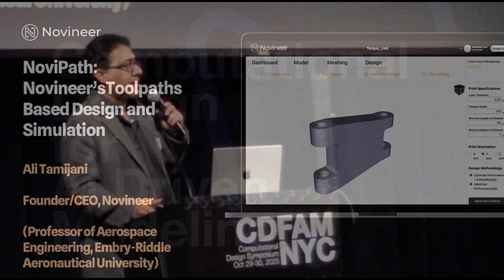The problem is that the load path doesn't have to be in one layer, right? And here we are talking about layer by layer additive manufacturing. The load path, depending on where you're applying the load, can be a curve, right? So if you have a kind of a robotic printer, then it's possible, as you can see for this case, to go from point of application, the two top holes, to point of support, which is the two bottom holes. But if you're using layer by layer manufacturing, 2.5D type manufacturing, then there is no way you can do that. The only thing you can do is try to connect the path in different layers, as I will show you later, right?